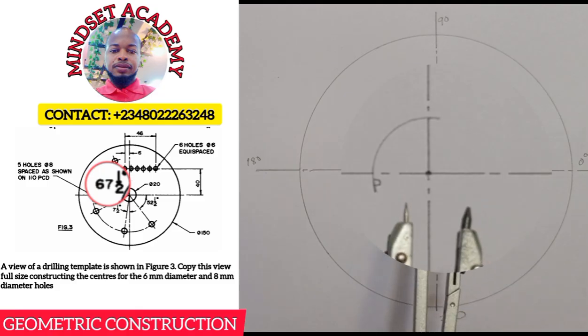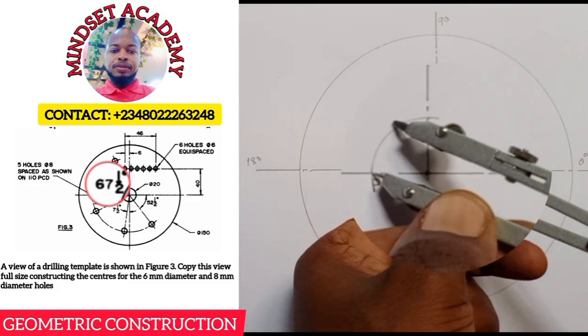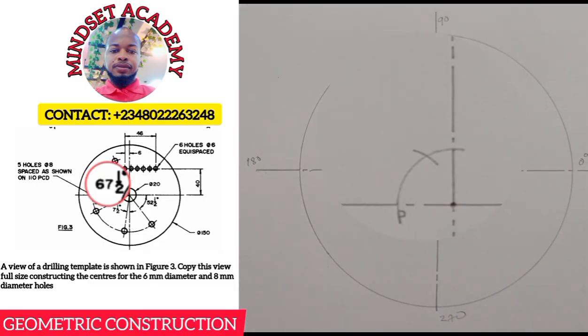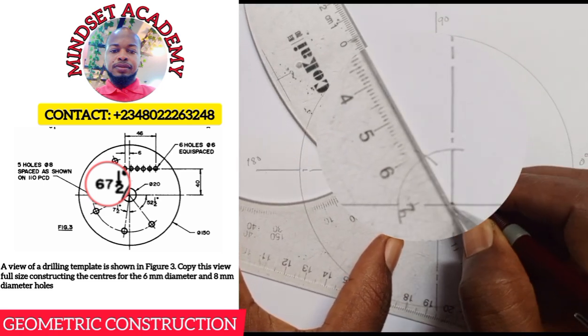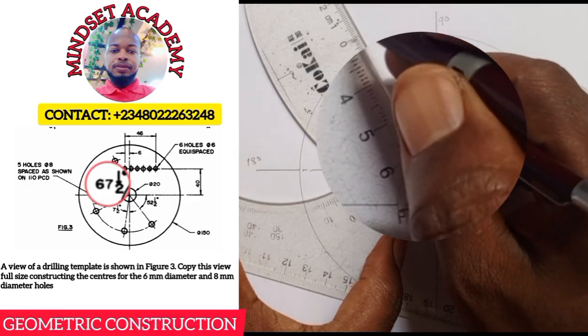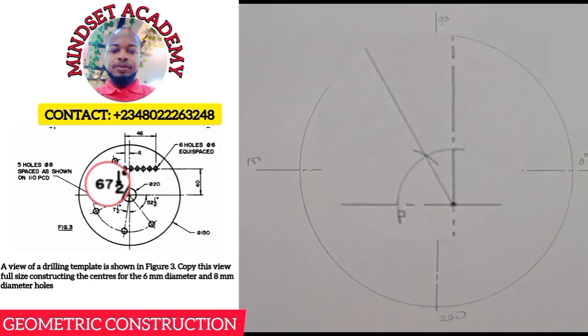With the same radius without changing it, I will now place it at point P. I will now strike another arc this way. Can you see that? So that arc I strike is given to be 60 degrees. So I'm going to just bring out the 60 degree line from that side. Can you see that? Just a faint line first. So this is 60 degrees.